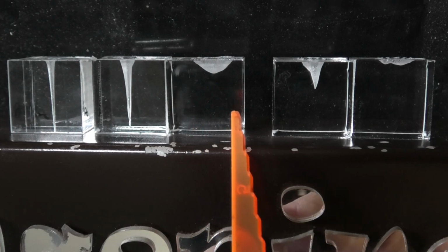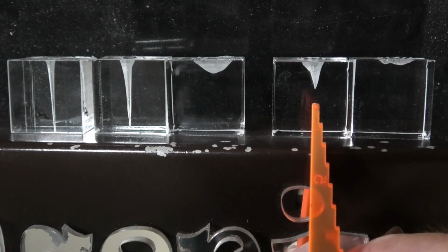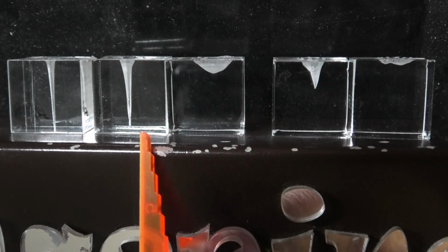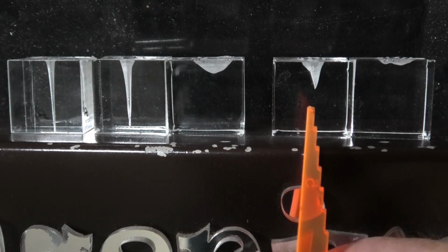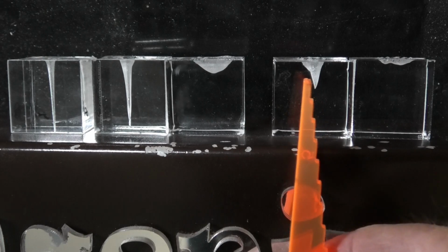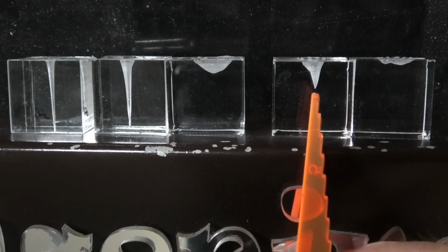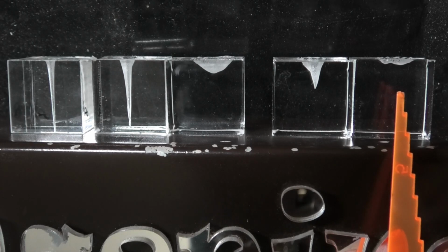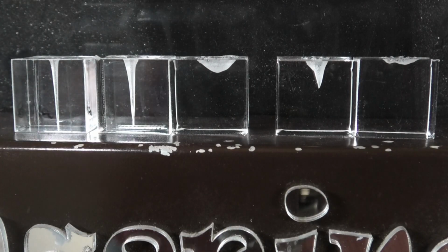So then I modified the machine with something called a beam expander. The beam expander is claimed to provide a uniform beam across the whole of the bed. Well, number one, as you can see, it's seriously depressed the intensity, because after 10 seconds, as opposed to 8 seconds, we've only penetrated this much. Look at the size of the beam. Yes, it has expanded the beam, but it's also compromised the intensity at the centre of the beam. And then a further meter on, look what we've got here. It's total rubbish. It's even worse rubbish than this one. These are all generated with a 30-watt beam.